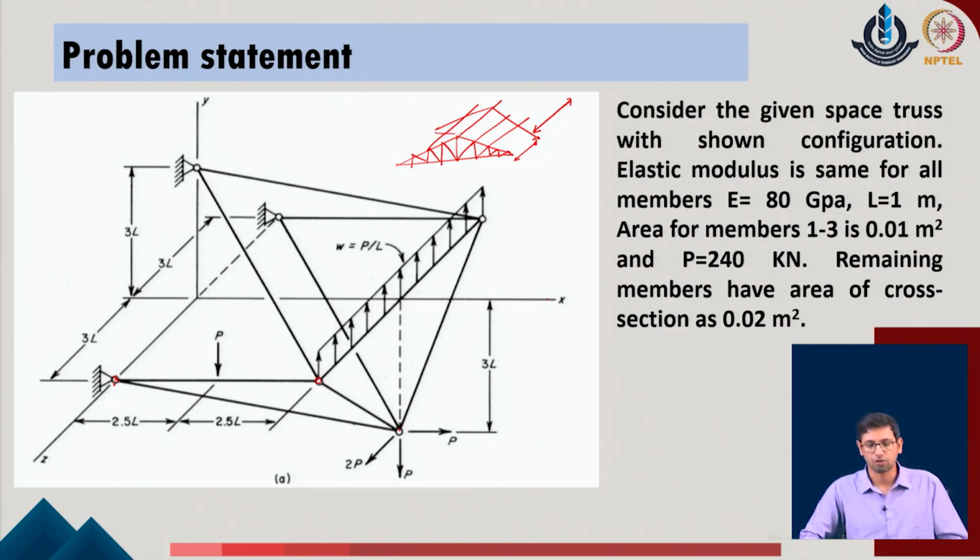So if you consider this as a part of the truss, if you make it in the same 3D manner, all these members will be connected. Now if we want to analyze the given system with non-uniform dimensions within these bay areas, one can consider that the overall space truss can be modeled and analyzed in the given structural analysis program.